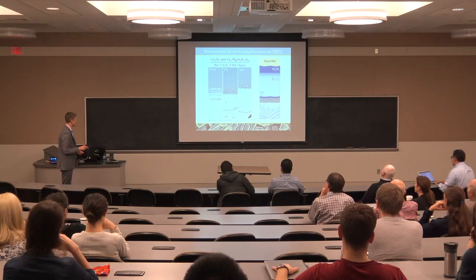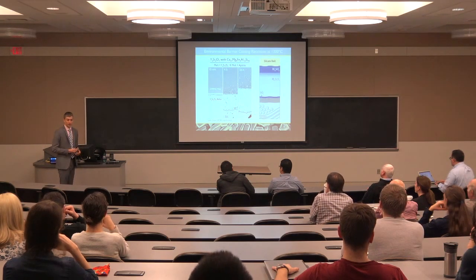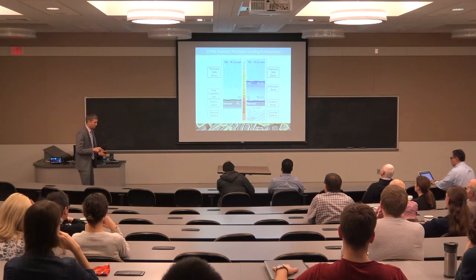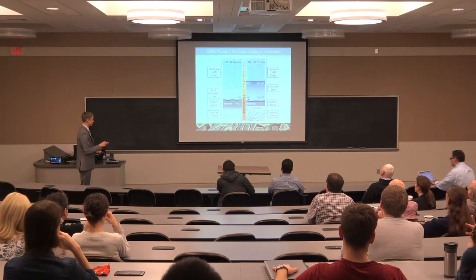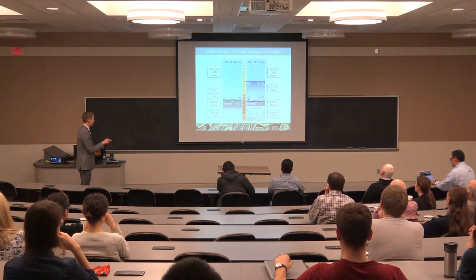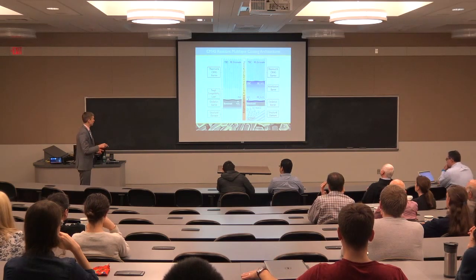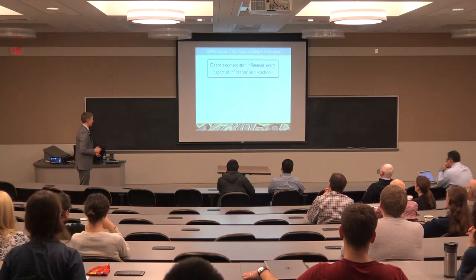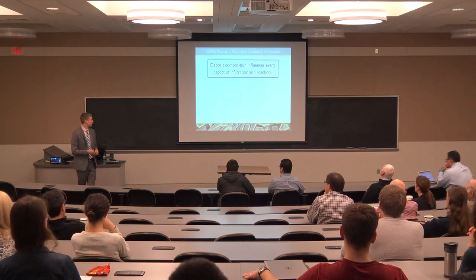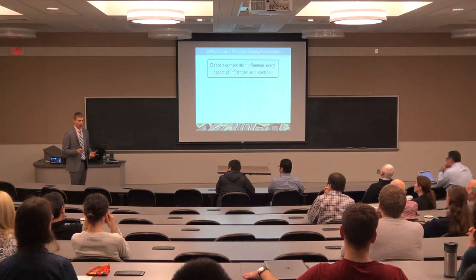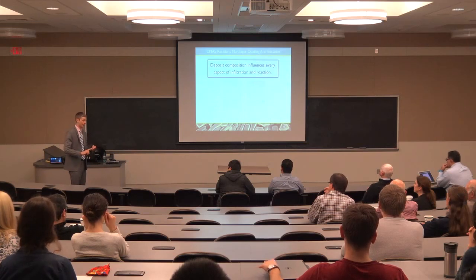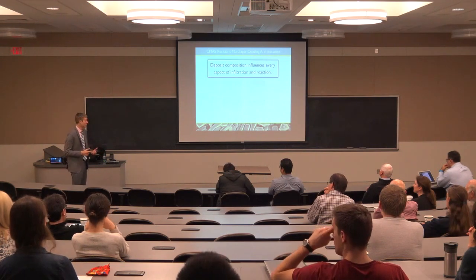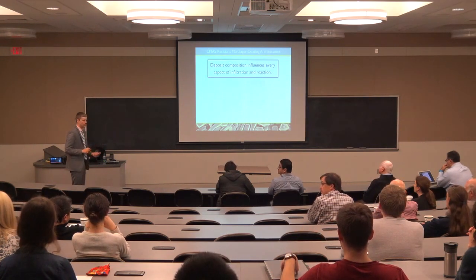And so in this case, we'd like to understand what drives the apatite precipitation reaction so we can prevent it from taking place. And another approach might just be, if we have a TBC material that works pretty well in preventing this mode of degradation, we could just apply an extra layer on the surface to protect the coating that protects the underlying structural component. But one of the challenges in designing these coatings is that every aspect of the degradation process, the viscosity, which influences the infiltration rate, the chemistry, which influences what phases are going to crystallize and at what temperature they'll crystallize, all depends on the composition of the deposit.